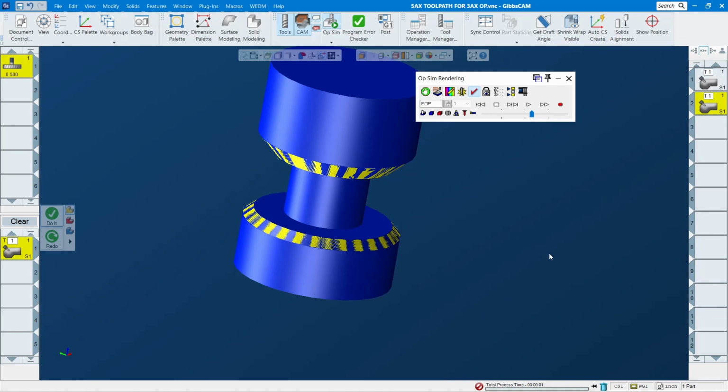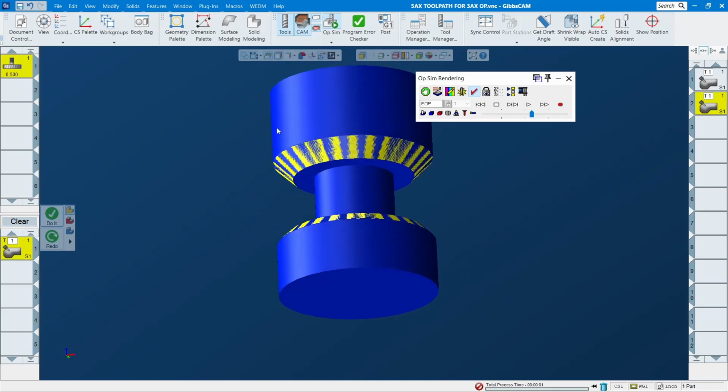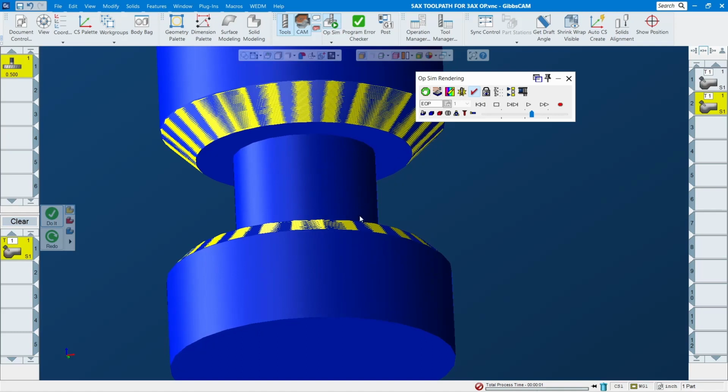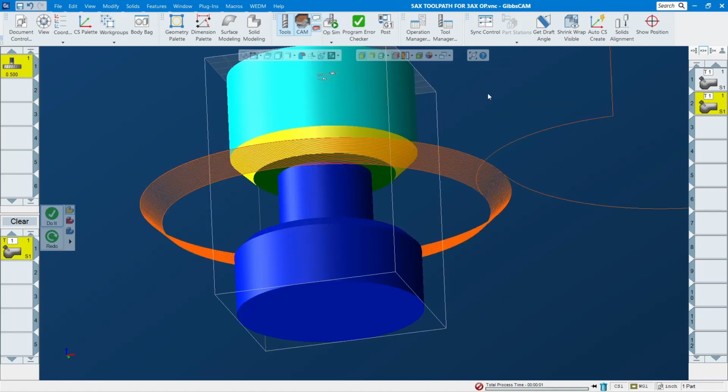So you learned something using this trick here, and like I said, it does not just apply to something simple like this. It can be more complicated, but it's up to you how you're going to apply it. The basic is the same: you map between 2 surfaces. Technically, I don't think I've done it, but you can do it with 2 curves too. You have to extract the geometry out and then do the same thing, but you select map between 2 curves.